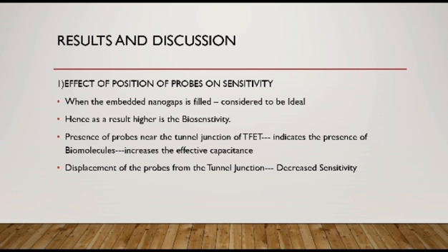The sensitivity in such a case depends on how the probe position influences the operation of the sensor. Hence, the result is higher biosensitivity. The presence of probes near the tunnel junction of the TFET indicates the presence of biomolecules and increases the effective capacitance. Displacement of probes from the tunnel junction decreases the sensitivity.